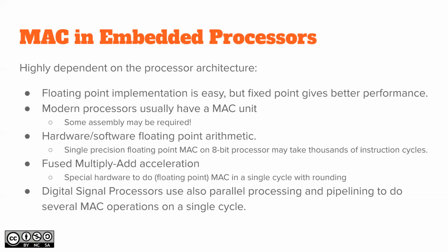And then we have floating point systems and we have fixed point systems. The fixed point digital signal processors usually give you better performance for the money. But if you have enough money to spend, then floating point digital signal processors give you at least a simpler way to do things, and sometimes the only way to do some of these applications.